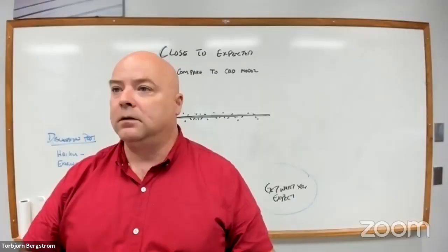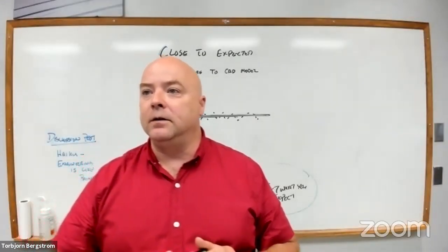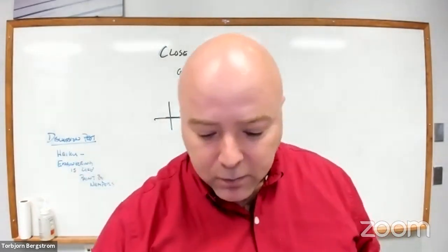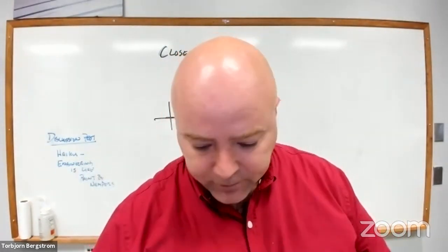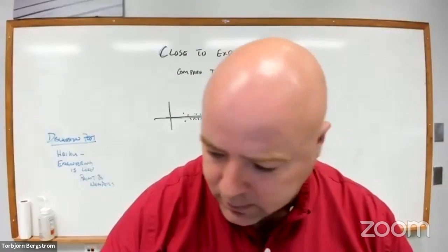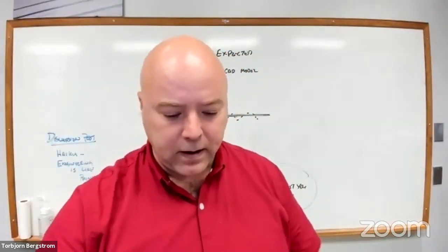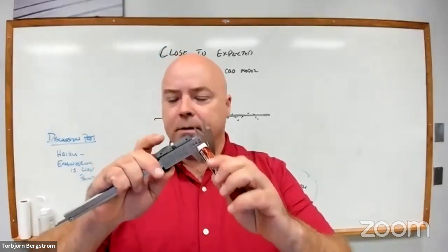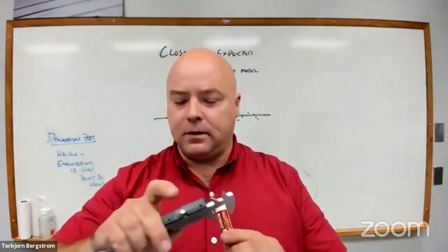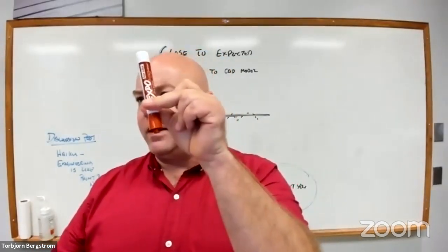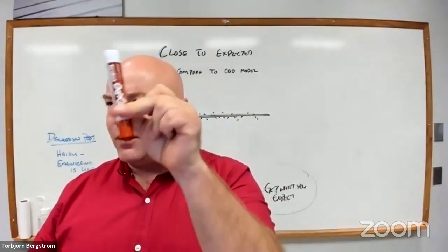It could be really close. It's certainly related to the true value, right? Mathematically, it's related to the true value somehow. Now, what if I took a measurement standard and I also used my calipers to measure the measurement standard the same number of times? And I know what the true value of my measurement standard is because it's certified.